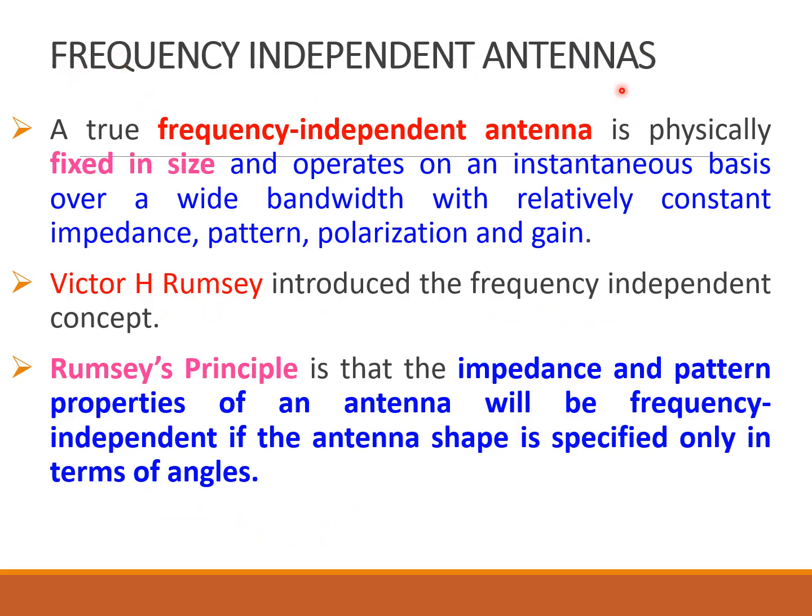Frequency independent antennas. Log periodic antenna comes under frequency independent antenna. As the name indicates, this type of antenna will remain fixed in size or the size will vary in proportion, right? And over the entire bandwidth, the impedance, pattern, polarization and gain of the antenna remain constant, and hence the name frequency independent antenna.